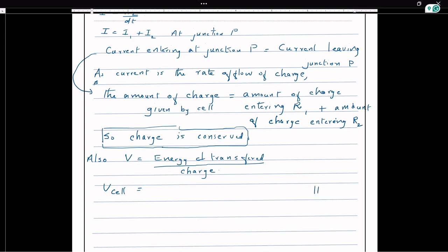So we have a loop with two resistors, and then this is connected to the next resistor C. This is C, this is A and B. So this parallel loop of A and B is connected in series with C. From that we can say that the cell voltage is distributed among the three components in such a way that the total voltage of the cell is the sum of the voltage drop across C plus the voltage drop across A or B, because A and B are parallel.